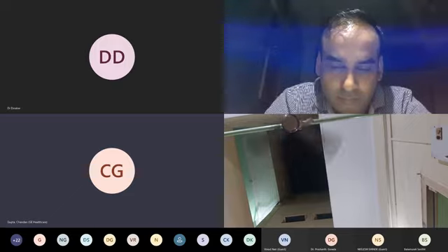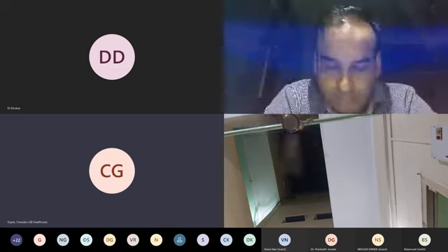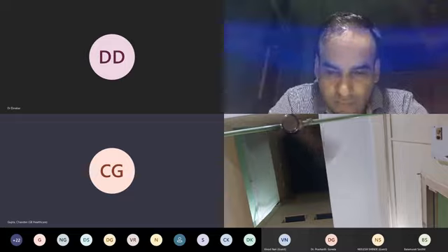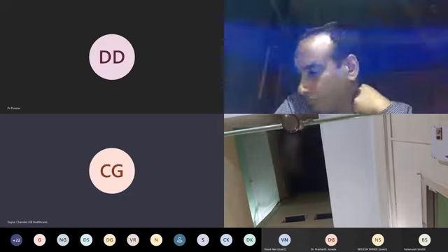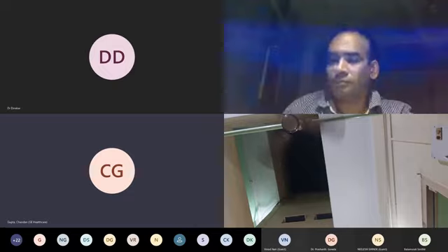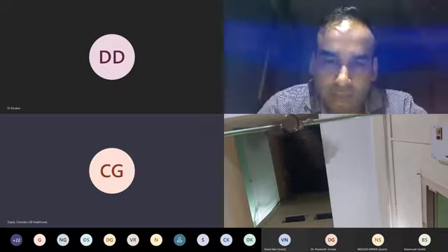Now when it is boiled to 100 degrees, most of the microorganisms will die. Not only that, whenever it is in a vapor form, the particles are so small that no microorganism can sit on that, because those are much smaller than any known microorganism. So no microorganism can come. That's the way you are ensuring that you are giving sterile humidity. So that technology is different from giving a moisture type humidity.